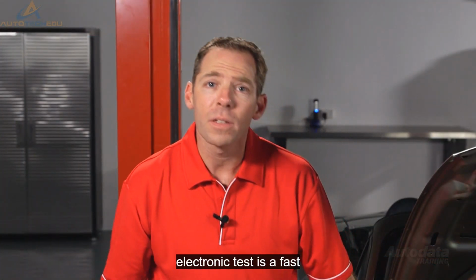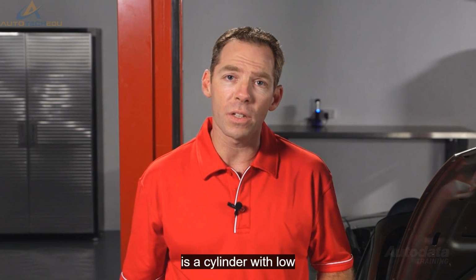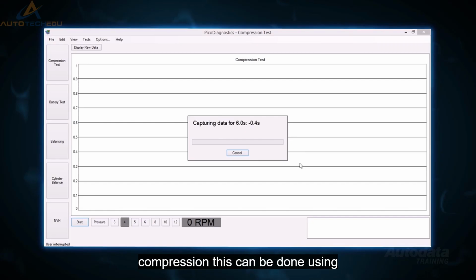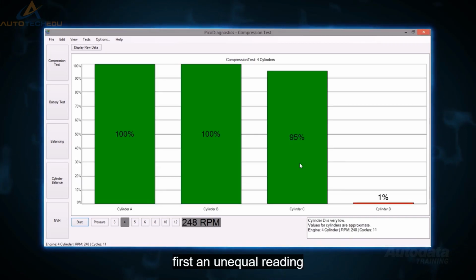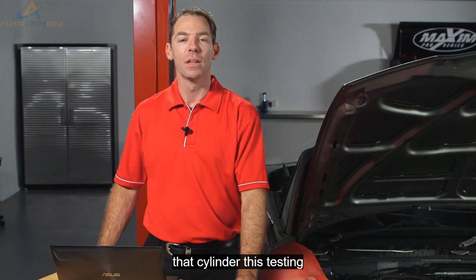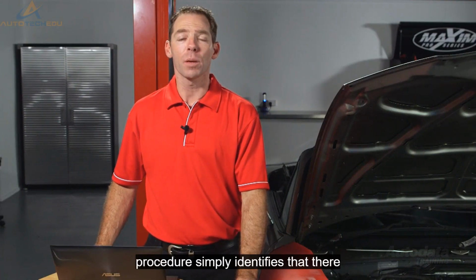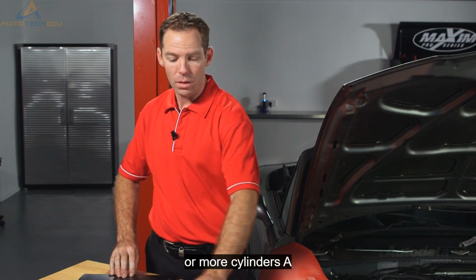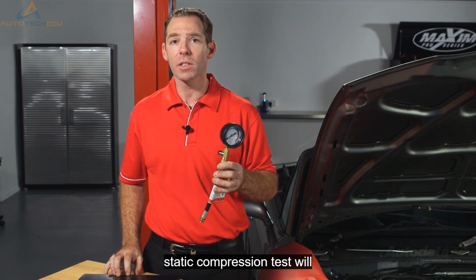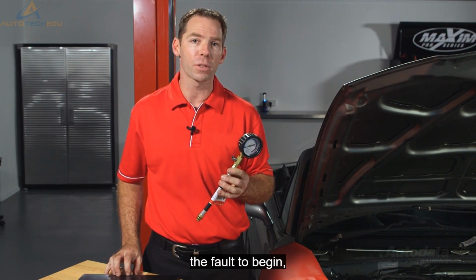An electronic test is a fast way of determining if there is a cylinder with low compression. This can be done using a scan tool or an oscilloscope. Let's have a look at this one first. An unequal reading can indicate a problem in the fuel, air, and ignition system or compression pressure for that cylinder. This testing procedure simply identifies that there is a fault in one or more cylinders. A static compression test will be required to pinpoint the fault.